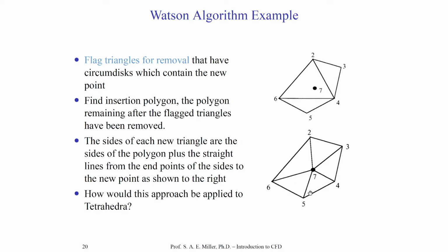Look at the number of cells, however. We have increased the number of grid points by 1, and of course we've increased the number of elements or volumes from 3 to 5. This increases computational cost, which is unfortunate, but on the other hand, we might be able to find a solution that is better posed for our solvers, especially in finite element and finite volume solvers.